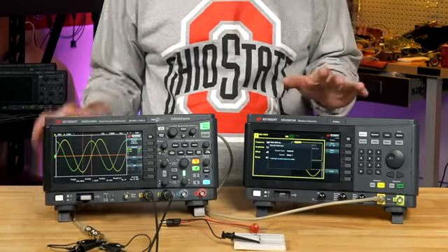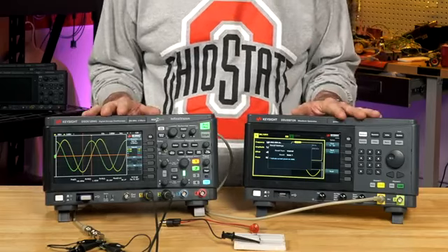The measurement we are going to perform is called a frequency response analysis test, but most engineers simply call it a Bode plot test. I'll start by showing you how to create a Bode plot the old traditional way, using an oscilloscope and a function generator, and then I'll show you a more automated way to perform the test if your oscilloscope has a built-in generator and automatic Bode plot capability.